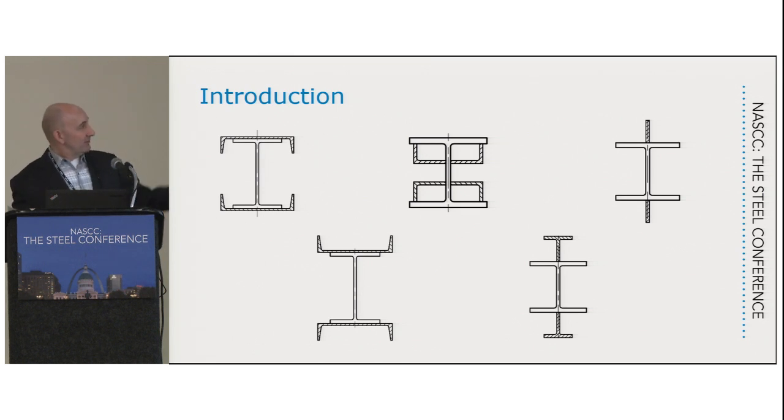For example, obviously this one's going to be pretty good for weak axis buckling, but watch out for weld clearance problems here. You can flip it around this way, but you're going to maybe lose space out on the floor. You're going to cut a few inches off of the usable space. One thing you can do is get a wider channel here to make sure that they can get access in there. This one, an architect may want you to do this so that he doesn't lose floor.